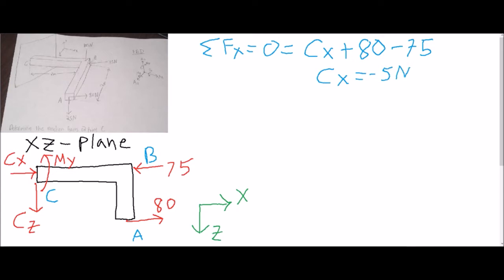That's the same thing as the xy plane that we solved, so we know we're doing something right. So next, solve for the forces in the z direction, once again 0. So look in the z direction. The only force pointing in the z direction is the reaction force at C. There's nothing else there. So once again, Cz equals 0. Oh, awesome. That's what we saw in the yz plane.